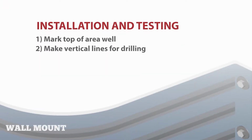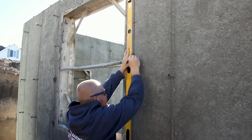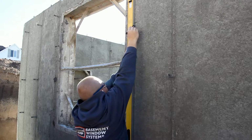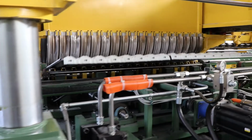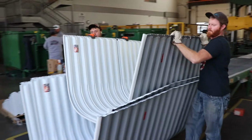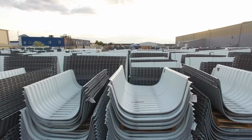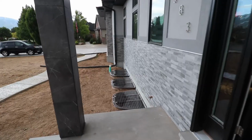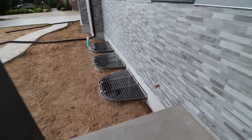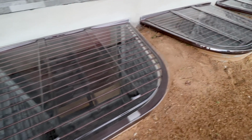Make vertical lines for drilling. Draw 2 vertical lines 57 inches apart. The numbers recommended in the table are important to follow so that a safety grate fits properly. The area wells are produced at the right specifications but have a tendency to relax and spread when handled and stacked for transportation. Using the centerline measurements will assure you of a proper look and exact fit for the safety grate and the Lexan plastic safety grate cover.